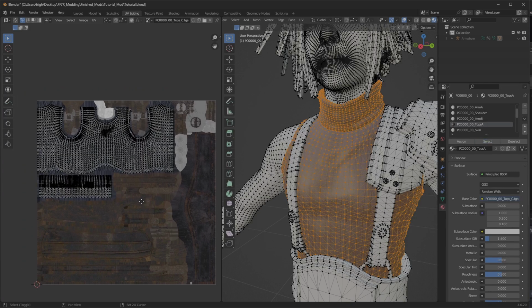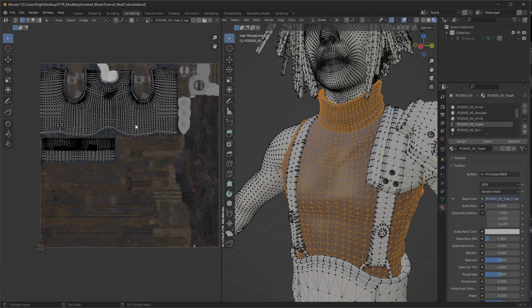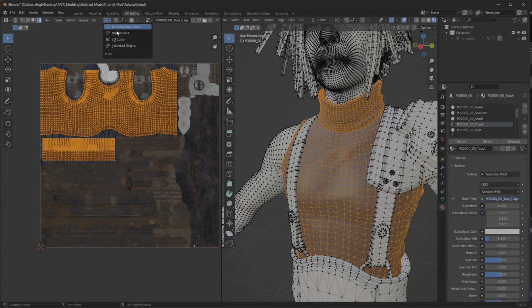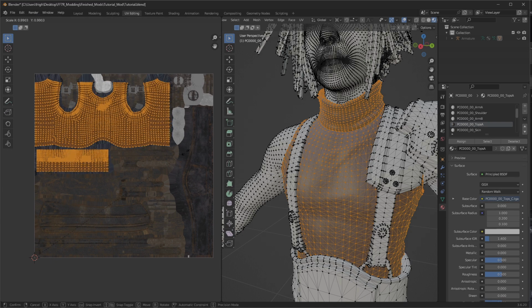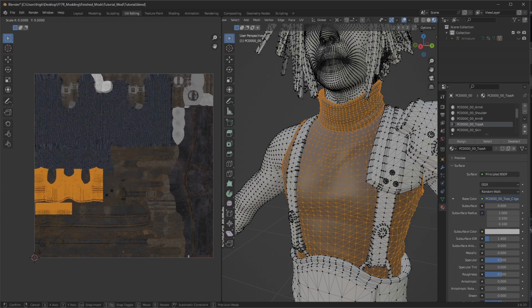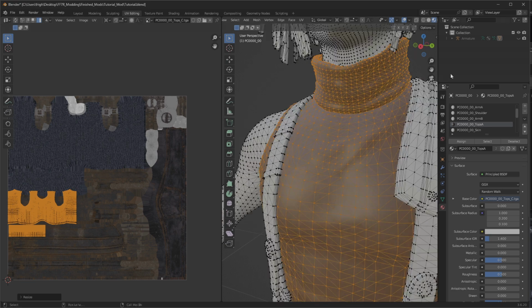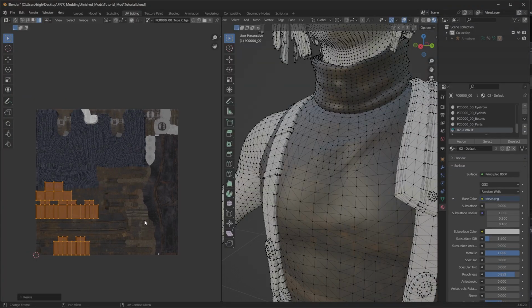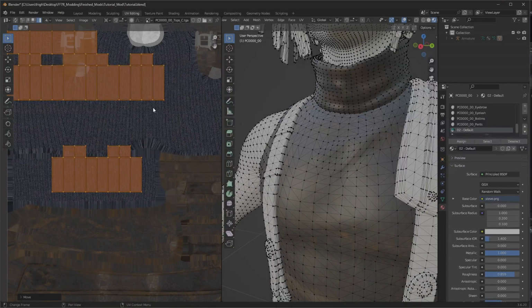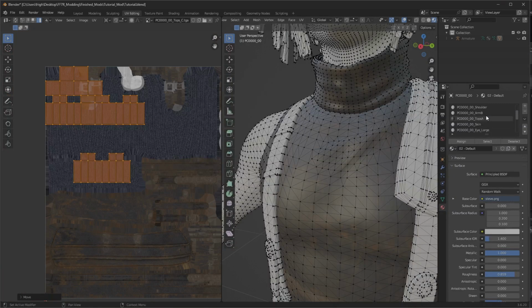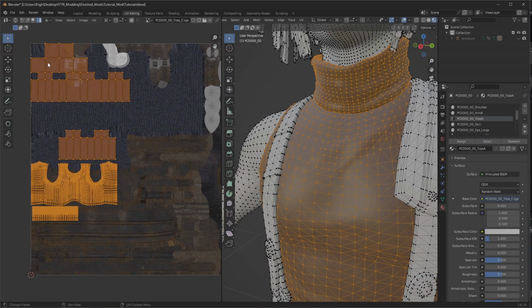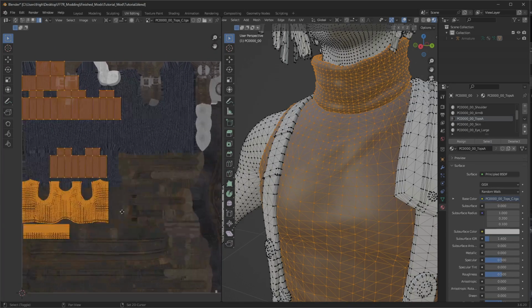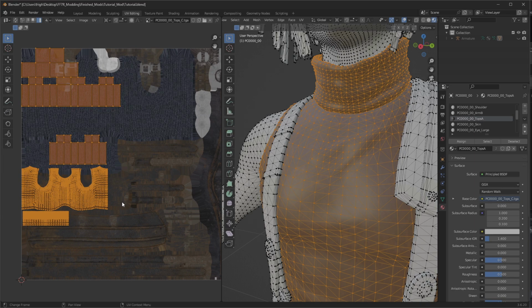So let's select this. Make sure that the scaling mode is set to the cursor. That way when we scale it down to around 50%, it will stay just here. I'm going to do the same with the Minecraft one, and just move it one unit up so it stays right there. If I select the top one once again, as you can see, they're both UV maps here. And that's all you need to do in Blender, really.